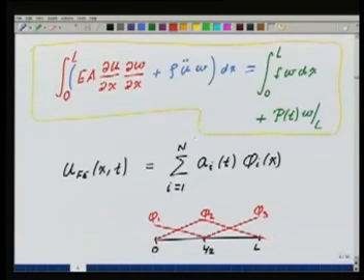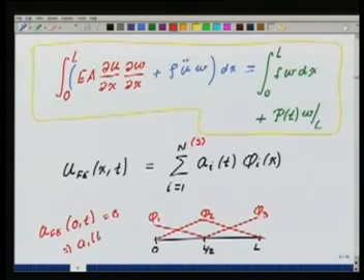So in this case, I could put n equal to 3, and what will my A1 be? A1 will come from the value of UFE at 0 is equal to 0, which implies A1 as a function of time would be 0. Okay. This we will not impose right away. We will do it when we have constructed the matrices. Then we will remove this part the way we had been doing and imposing the boundary conditions in the static problem. So we will continue with this representation and then do the rest.